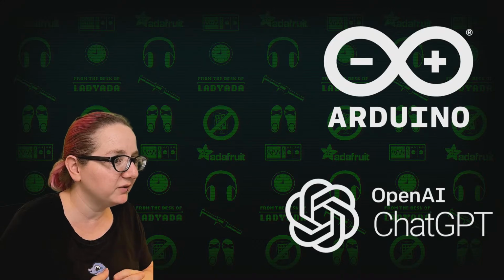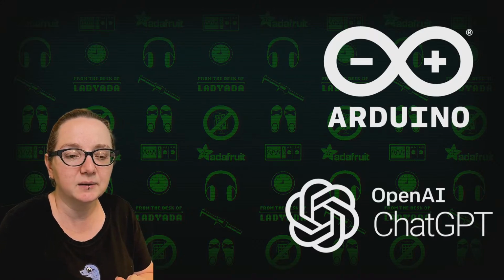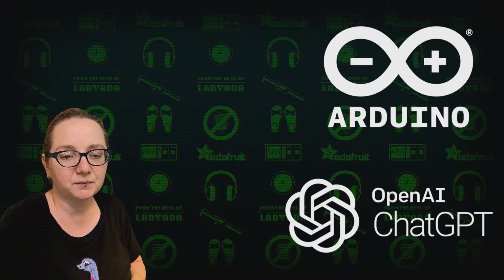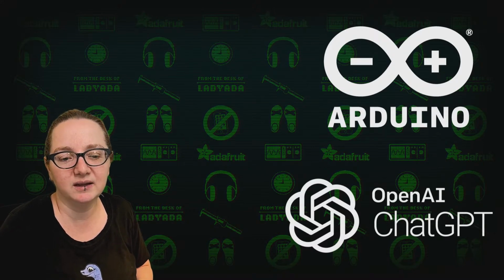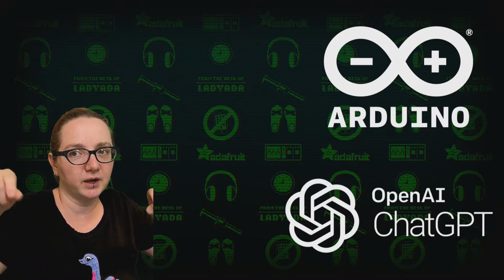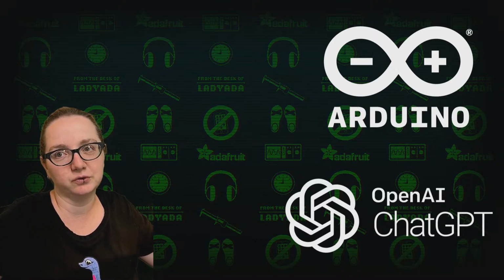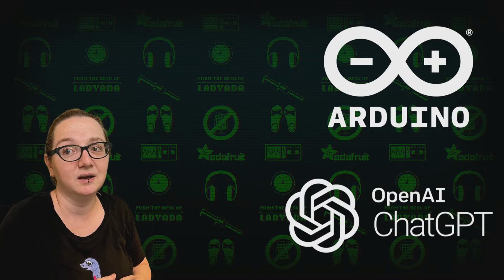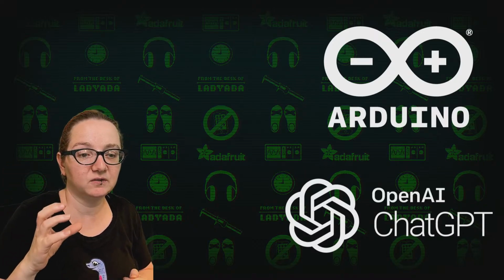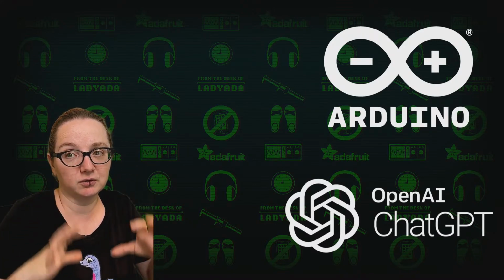So eventually a few days ago, I was like, oh, you know what? You were showing me the PDF importer, and I was like, maybe I'll use this plugin. And I started by copying and pasting parts of the PDF, and I said, I want you to reformat this into an enum, because one of the things that's very tedious about writing libraries is you have to get the registers out, and it has to be like #define CHIPNAME_REG_CONTROL1. #define CHIPNAME_REG_CONTROL2. And then continue. And there can be like 50 registers easily. And then on each one, you have the enumerations for the actual capabilities. So even within those 50 registers, you can have 4-bit wide sub register configuration sections.